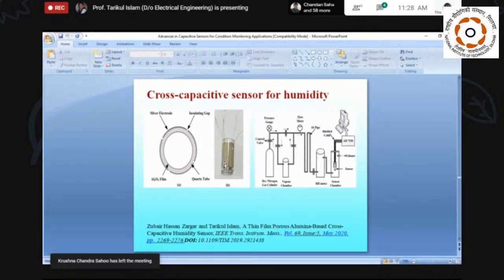We place 4 cross electrodes on the outer surface of the quartz tube. So this is a quartz substrate cross capacitor. Inside there are 2 dielectric layers: one is the glass substrate and another is the moisture sensing film. So it is basically the structure shown here. This is a quartz tube. Inside there is a moisture sensing film, an Al2O3 film, and outside there are electrodes.